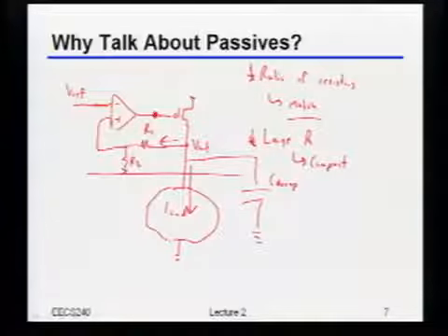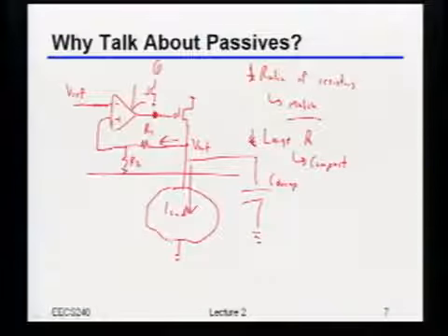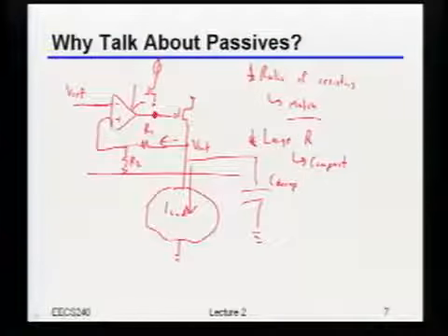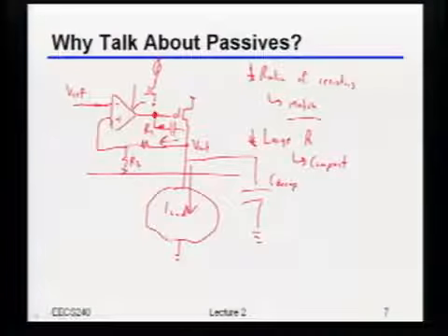Especially if I just built this out of, let's say, a common source amplifier. Obviously this is not exactly it, but conceptually something that looks like that. It's a high impedance node, so I'm going to need some sort of compensation network. What's a common compensation network I might use? The capacitor. Okay, you said a Miller cap. I think you said an RC. So let's go and do some RC thing like that.